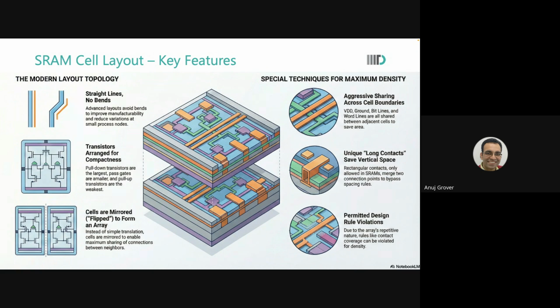Now, do you think that the device modeling team has put every possible size on silicon to build a model for you? No. They made a size 0.2, another size 0.5, another size 1, another size 2, then 5, then 10. A company may not have made 5 at all and gone straight to 10. So they assume linearity, piecewise linear. Okay. But with piecewise linear, what happens?